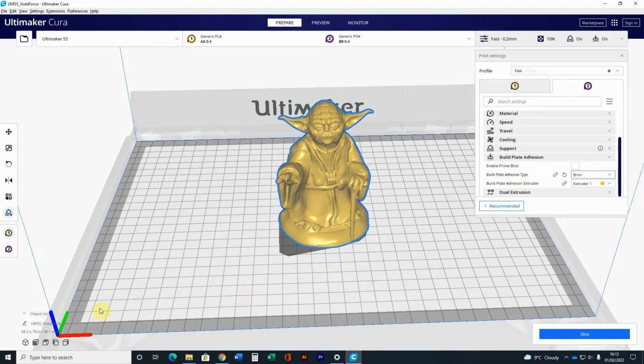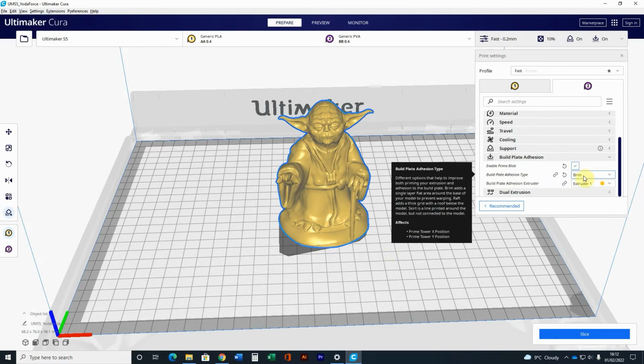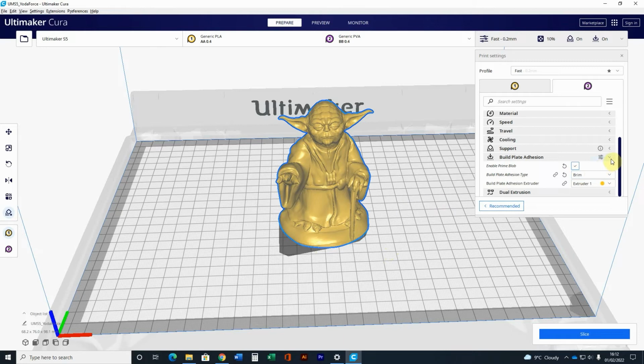What it does, it goes down to the bottom left corner and it primes the nozzle and extrudes out some of the filament before it goes straight to printing. So we make sure that it prints straight away, because if it doesn't start extruding perfectly at the start, it can mess up the whole process. Okay, so I sometimes click that. You don't tend to need to use it if you're printing a brim or a raft, but it's just good to know.